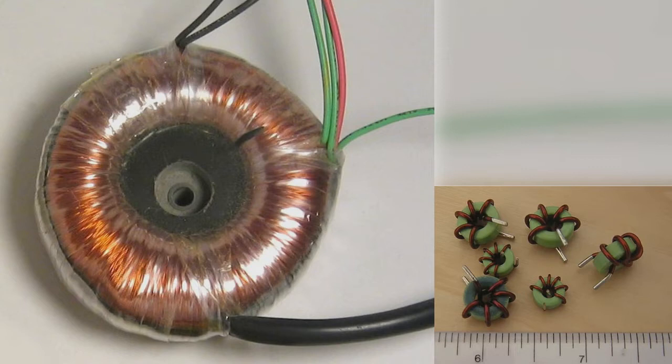And in power supplies, because they're more efficient than regular old iron cores that would typically be in a power transformer, and it doesn't take as much area. So they can take a single height rack unit and put the power supply in there, and they can still have high current and not as big a transformer for the power supply. Yeah, interesting.